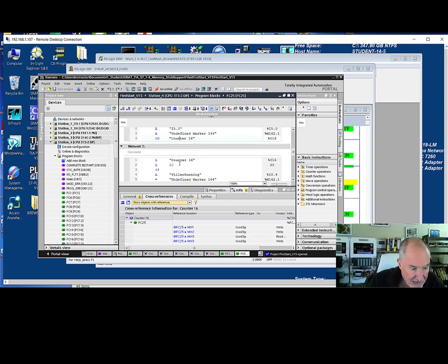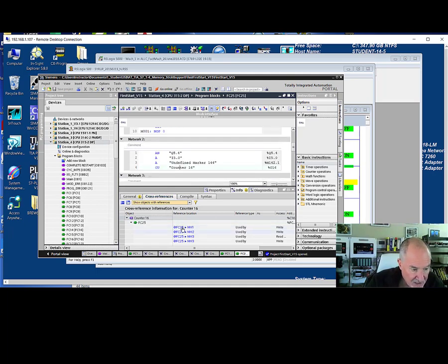A lot of times you'll find the counter here, but let's say you cross-referenced it and you landed here, and you can see that Q5.4 has to be off, right? This is a normally closed for Q5.4, and I5.0 has to be true. So once again, kind of a difficult example because we're in statement list and because we don't have any symbols.